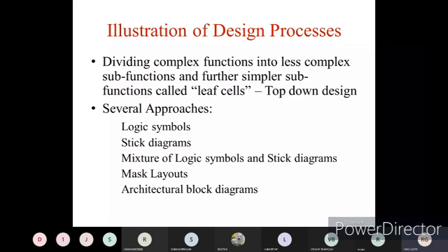When you want to design the elevator for your home, you need to think about what area is given for the elevator, how many passengers, that is, how many family members can use the elevator, what height of elevator we need to design, and what power is available at home, which we need to consider. So the first step in a design process approach has to be the design requirements, collecting the specifications and requirements from the user.